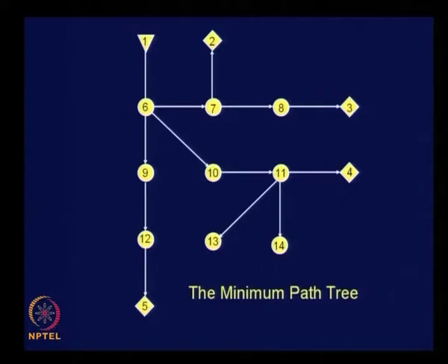So, this is the minimum path tree. So, we will be assigning traffic from 1 to all the other points of interest following this route only as per user equilibrium assignment methodology. Is that clear? So, please understand that the link array can be given as input to get the minimum path tree from any node of your interest.